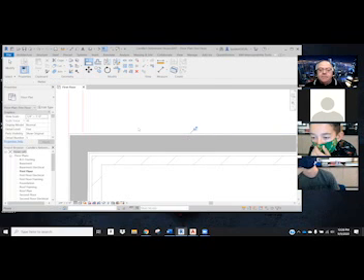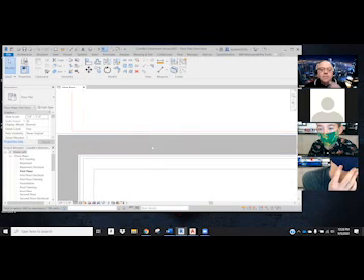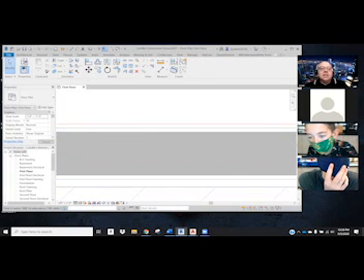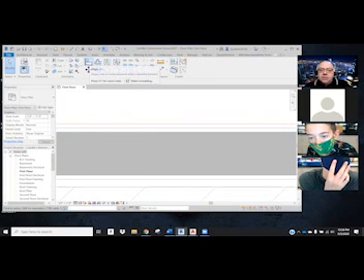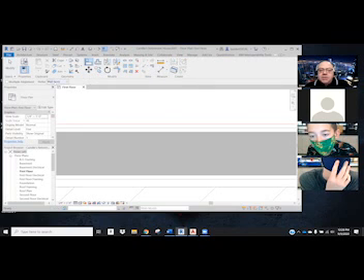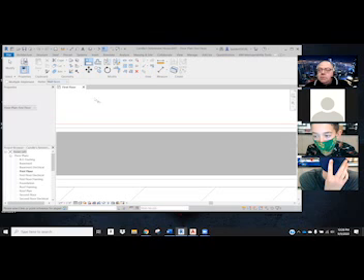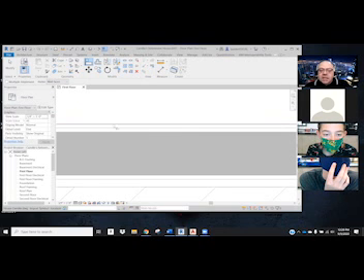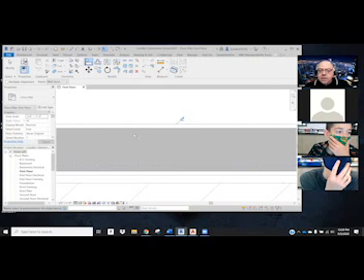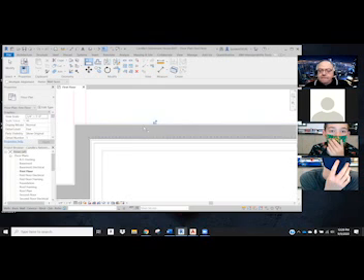And then do that again so you guys can see it. Okay, so I'm going to get really close. I click on the Align tool. I make sure I'm on wall faces, and you might have to redo the command again to get that to activate. I select the line where I want to go, and then the line that needs to go there. So pick your destination and then what's moving, and it will move it right into position.